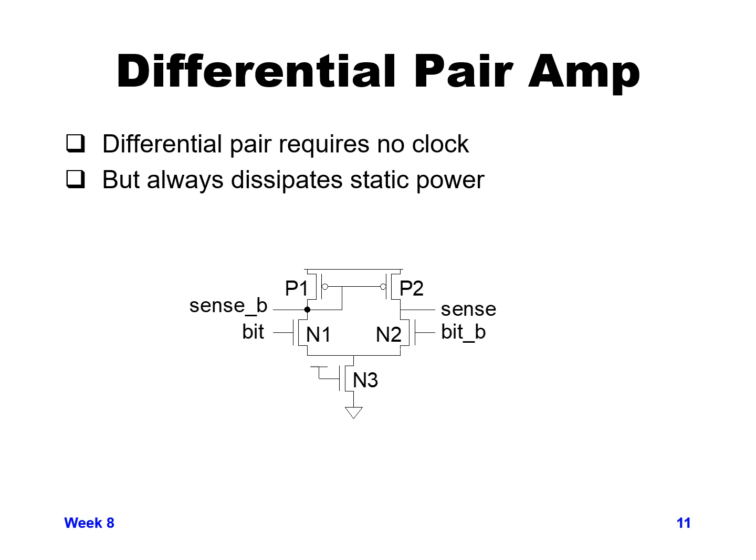On the bottom, transistor N3 acts like a current source, and N1 and N2 are a differential input for, in effect, a voltage amplifier, and P1 and P2 are in effect a current mirror load on this differential amplifier.